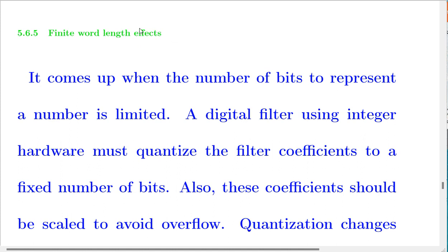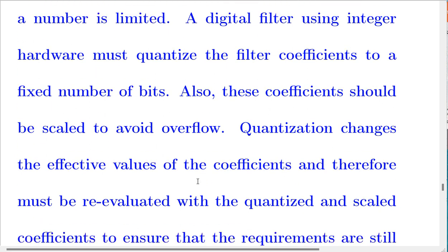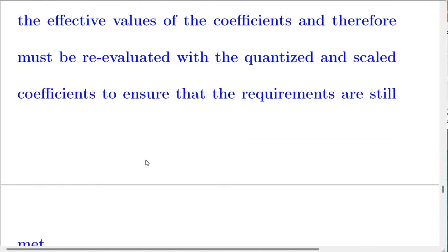Finite word length effects. It comes up when the number of bits to represent a number is limited. A digital filter using integer hardware must quantize the filter coefficients to a fixed number of bits. Also, these coefficients should be scaled to avoid overflow. Quantization changes the effective values of the coefficients and therefore must be re-evaluated with the quantized and scaled coefficients to ensure that the requirements are still met.